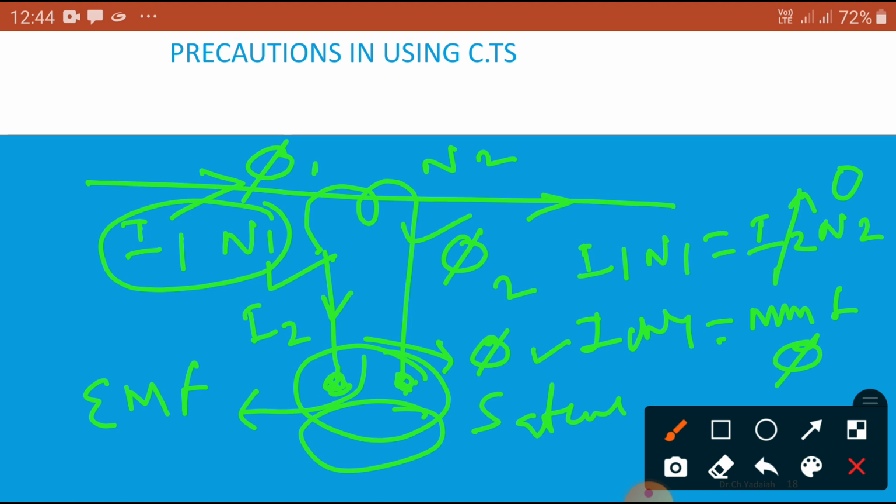So sir, if I want to remove this, then before removing it, short it. What will happen? The current may not be equal to 0. It produces its own flux, which is always opposite to this flux. Then whatever flux is in the core is limited. No dangerous voltage is produced across the two terminals. Okay, so that is the one thing you remember.